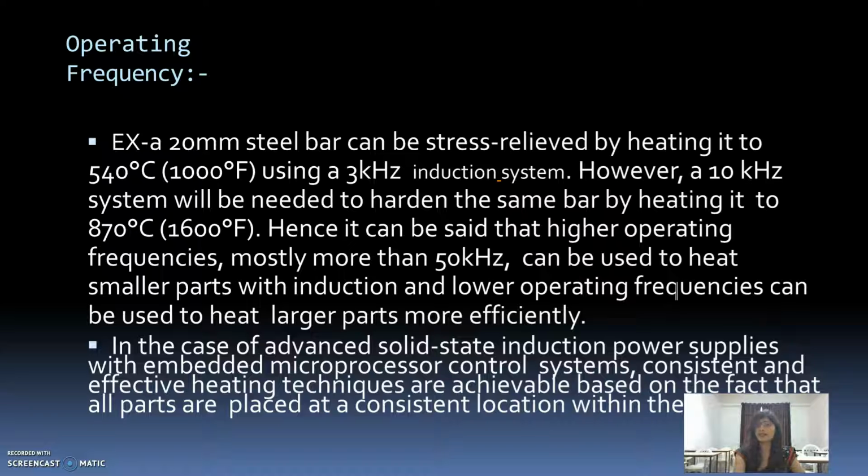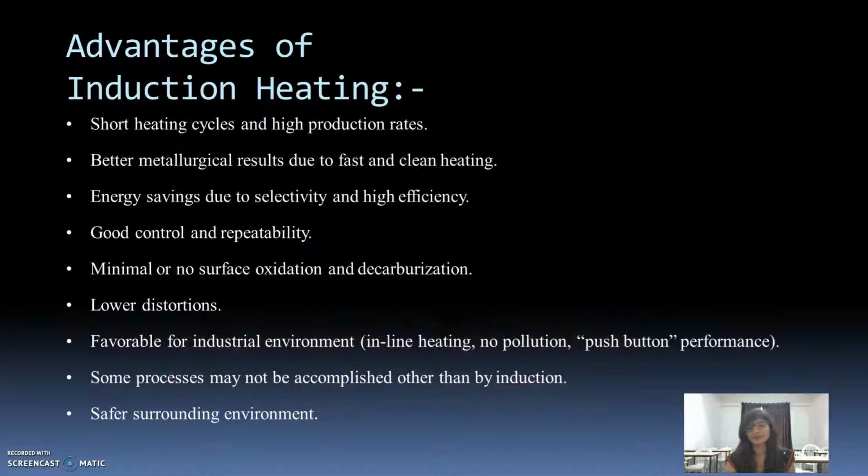Hence, it can be said that higher operating frequencies, mostly more than 50 kHz, can be used to heat smaller parts with induction, and lower operating frequencies can be used to heat larger parts more efficiently. With an advanced solid-state induction power supply with an embedded microprocessor control system, consistent and effective heating techniques are achievable, provided all parts are placed at a consistent location within the coil.